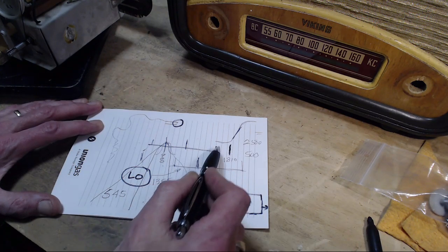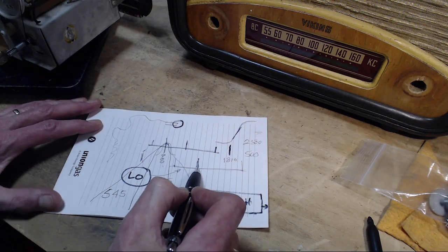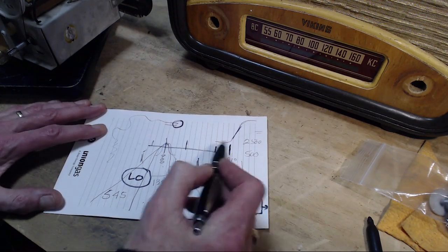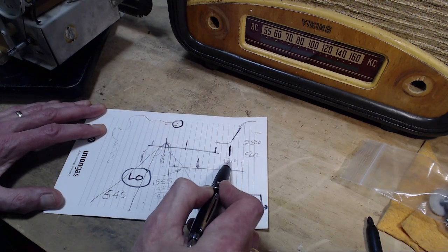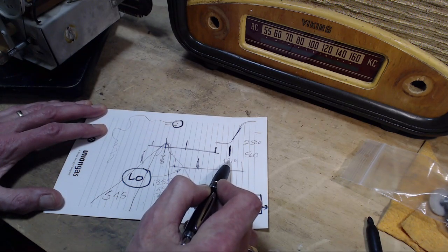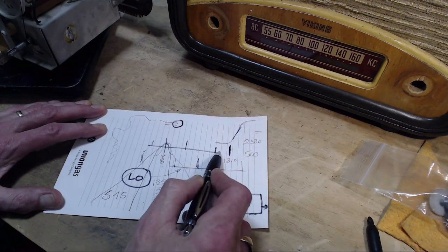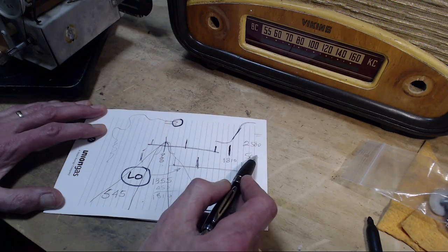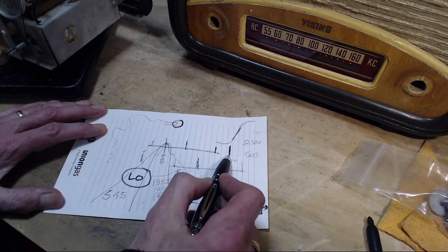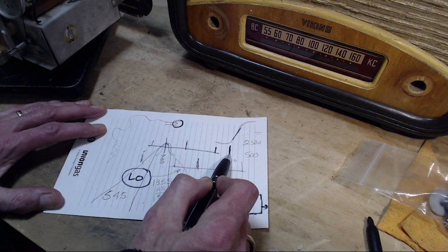Now, my first example: 900, 1355, 1810. You see 1810 is actually beyond the AM band. And what is out here? In my case, a lot of noise. So there could be a big noise signal at 1810, but there won't be any radio signals.